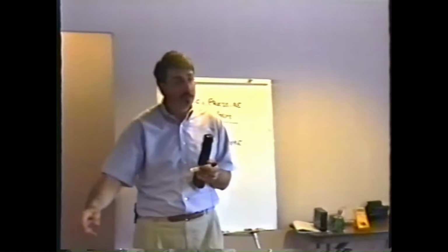So we will measure voltage with our meter. And there's volts DC, volts AC, which we'll talk about the difference in just a minute here. And we will use our meter to measure volts. We will not use the meter to measure current, to measure amps at all. We're never going to use that amp setting, even though it's there, and we could do it, we're not going to ever do it. And then this is where the meter would be set for ohms.